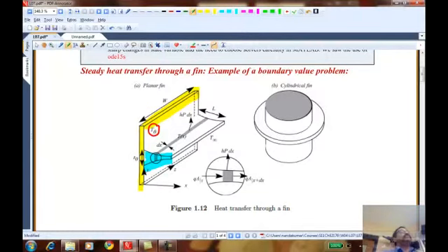Okay, so in the case of a CPU heating up, we should be able to estimate how much heat the CPU is putting out, and so what its temperature at the top is likely to be. From there, you want to conduct that heat away. So the mechanisms that are helping in taking the heat away from the base, that is from this surface, and transferring it this way along the length of the fin. The length of the fin direction, we call it X.